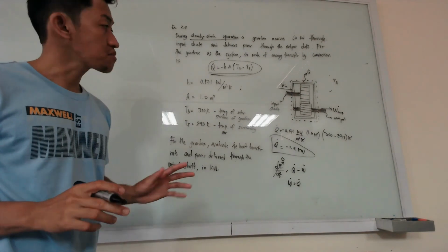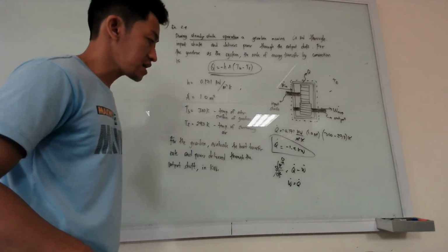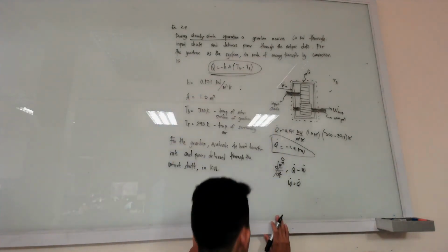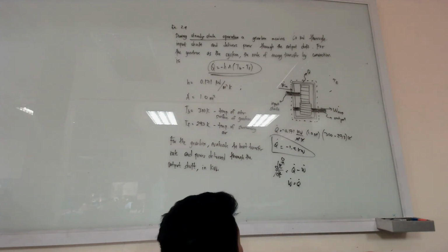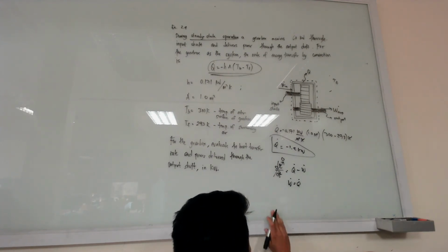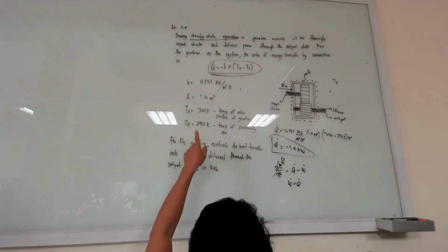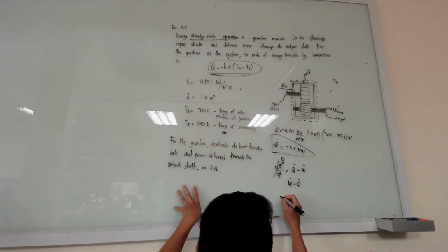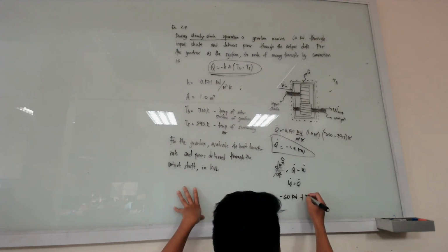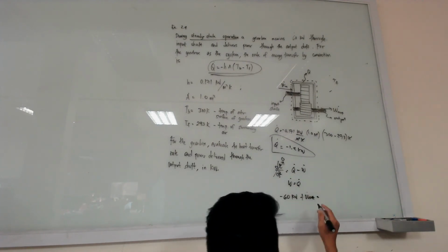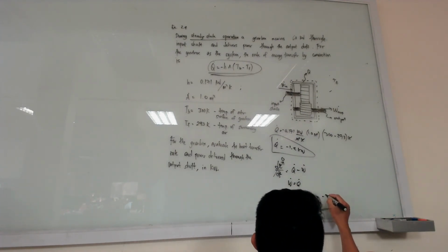So here the importance of your system boundary plays a role. Okay, so based on your system boundary, by notation, if the work is going in, it is negative. So therefore that 60 is negative, negative 60 kilowatt because it is going in, plus work out, work done by the system, positive, is equal to Q, negative 1.2 kilowatt.